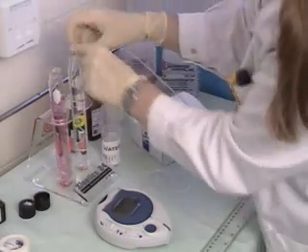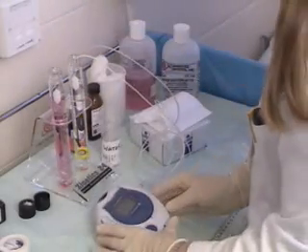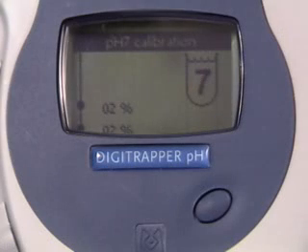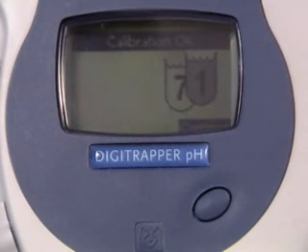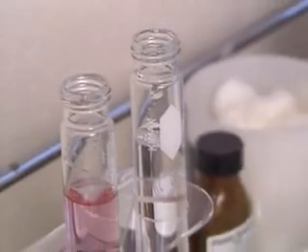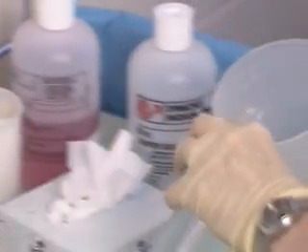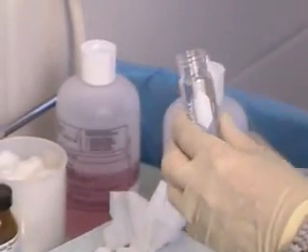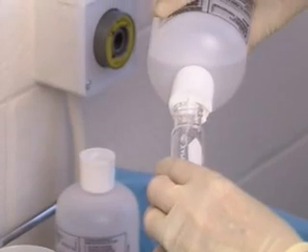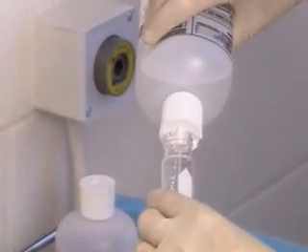Make sure that each of the sensors and the reference electrode are immersed in the buffer solution. The unit will now check the catheter function. Once stable pH values, firstly from pH buffer 7 followed by pH buffer 1 have been obtained, you are ready to begin recording. Discard the used buffer solutions after calibration. Contamination of the buffer solution should be avoided, as this can create calibration problems and potentially inaccurate results.